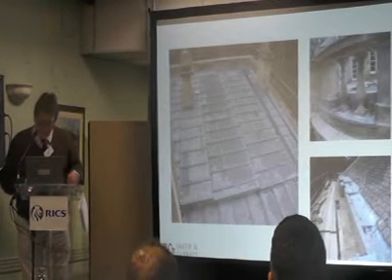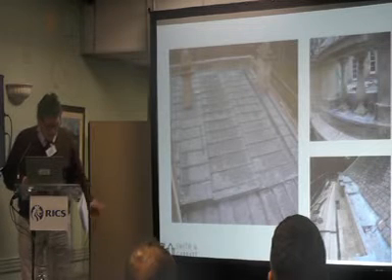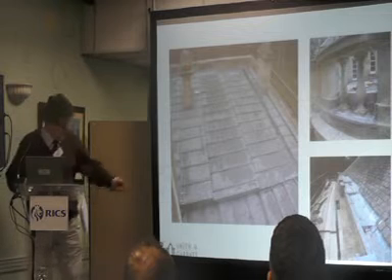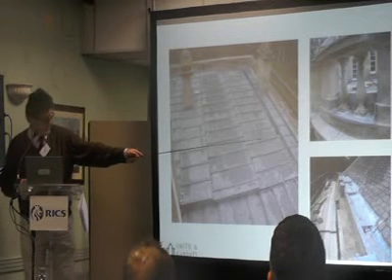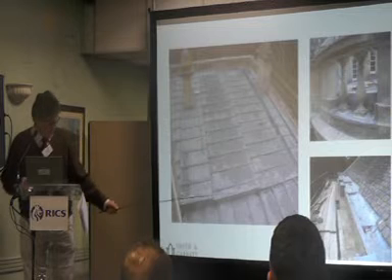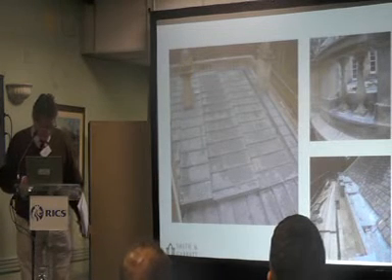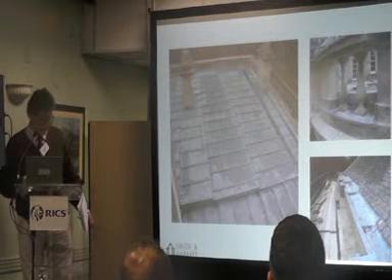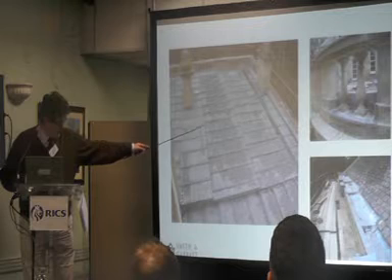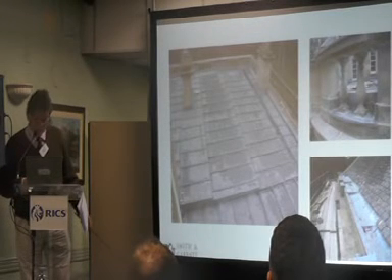this is all actually the same building, work we were doing 2 years ago. The large roof is code 7. The trim with the ventilation detail circled is code 5, and the gutters are code 7 again. We have ventilation hidden in here around the chimneys and along the edges, along the margins. You'd never know it was there, but it is there and it's absolutely vital.